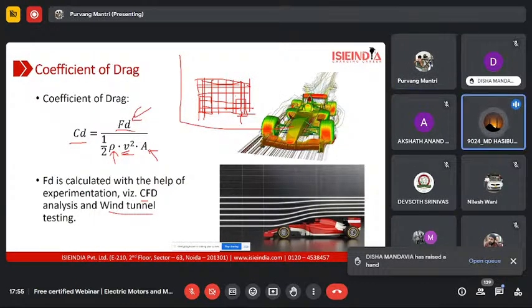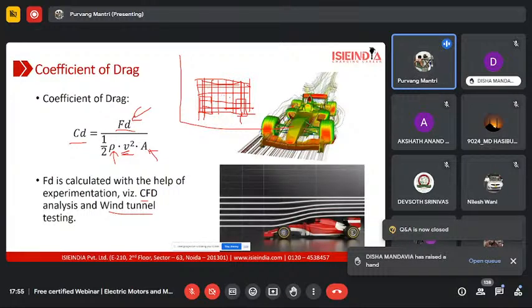Sir, the horizontal grid. Yeah, so once you have created the grid, you know that if these lines are 1 centimeter apart, then the area of one block is 1 centimeter square. Then just calculate how many blocks are entirely covered by the car. That will give you a basic idea of how much the frontal area is. Add up all the blocks and you will get a certain centimeter square value. Multiply it with the scale and you will get your value in meter square.